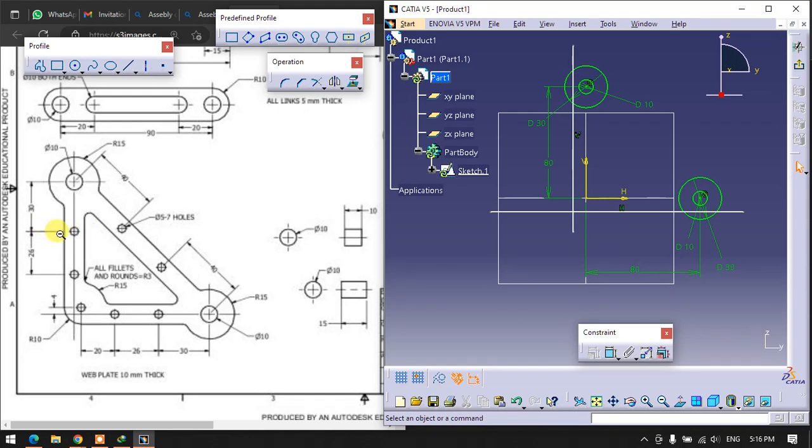This circle should have more than 5, and also the distance between these two is given as 4, that means the distance from here to here also has to be more than 4. So simply I'm going to follow this one, which is given as 4 here, the same distance, and try to catch here. Select this one, this one, and I'm going to specify 4 thickness. If I select this 4, can we create a circle here? So I'm going to create one circle for sample's sake, and provide a radius for this circle as 5. Is it fitting there?